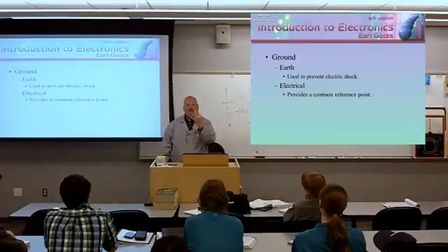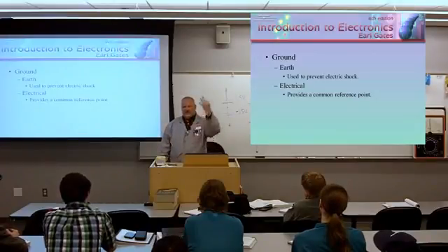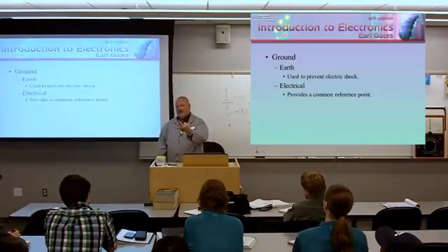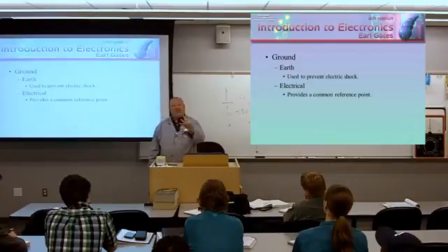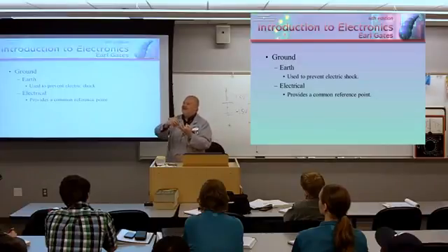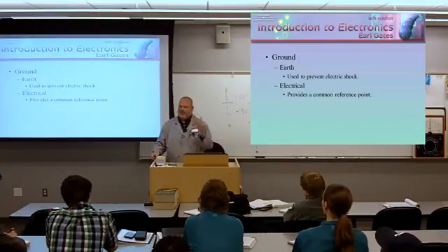I've got a satellite receiver with the antenna up on the roof. That antenna needs to be referenced to ground. The satellite receiver also plugs into the electrical outlet that should be referenced at ground, and it also needs to be plugged into the telephone connection that should be referenced at ground.